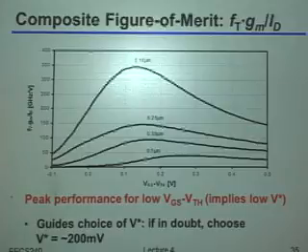Yeah, okay. So you said you get better efficiency there. And why is that okay if I'm scaling from one technology to the next? Why can I afford to actually get that better current efficiency? Yeah, okay. So you said you're trading off FT for it, right? So to the extent that scaling the technology actually gives me a faster transistor, I will tend to push that V star down so that I can exploit the fact my transistor got faster and bring me back to the original bandwidth I wanted in the first place, but just get better current efficiency out of it, right?